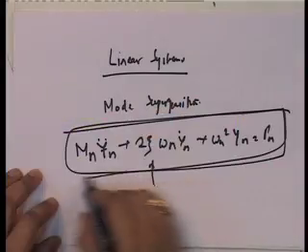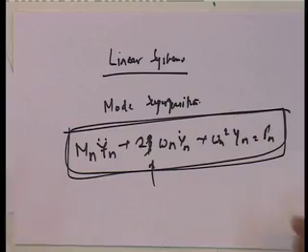If xi is the same in all the modes, then who cares? In a way, you may say that by taking xi, I am assuming Caughey damping. You can say that, it doesn't matter. But you do not have to evaluate A, B. You are solving modal amplitudes and you are assuming xi to be the same in all the modes. This is an assumption. So, to consider damping, it is not relevant whether it should be mass, Rayleigh or Caughey.